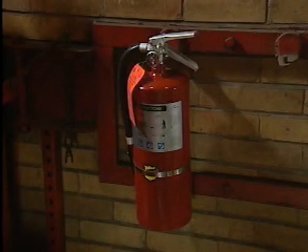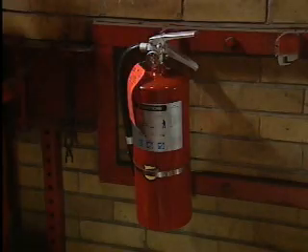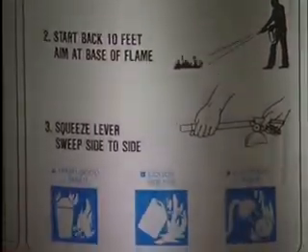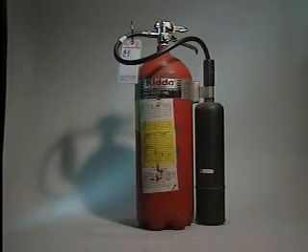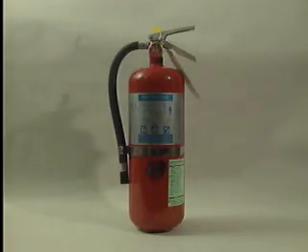If you need to use a portable fire extinguisher, make sure it's designed for putting out electrical fires, which are Class C fires. A fire extinguisher that's rated Class A, B, C can be used for almost all types of fires, including electrical fires. Three types of fire extinguishers that may be available are carbon dioxide fire extinguishers, dry chemical fire extinguishers, and halon fire extinguishers.